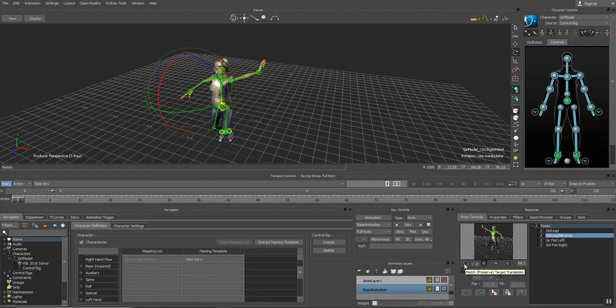Now, if we look at the translation here, what we could do is preserve X translation, Y, and Z. If I shut off rotation here, what it does is it gives me this mirror plane option, which you can toggle on and off using this eyeball. And you can see there's ZY, there's XY, there's XZ, and then there's this custom option, which allows you to pan this particular value here.